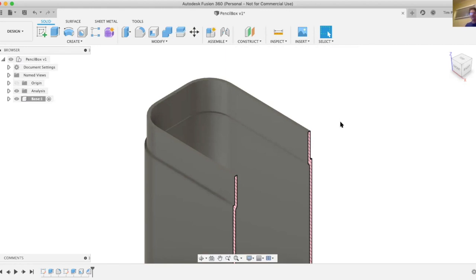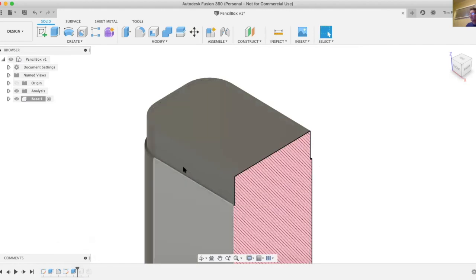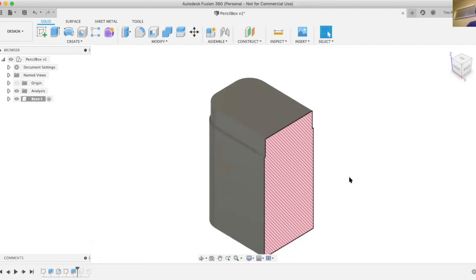Okay, great. Thanks for the questions. And that's exactly what I want you guys to do. So I'm going to back up to before the shell. I'll leave the cross section in for now, but I'll explain it a little bit different, a little bit later. But so this was a solid body that I created. Now, often when you design plastics for injection molding, for example, and there's a lot of other cases as well, you want a fairly consistent wall thickness. So you can create an object like this that you can have all kinds of complication in it, and then at the appropriate time, you want to effectively hollow it out.